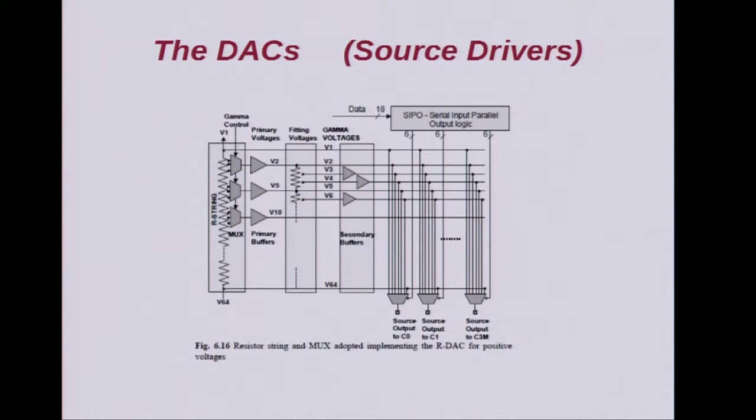The problem is that from month to month the mix of LCD material wasn't the same. It came out slightly different. Manufacturing tolerances of printing these LCD panels, all the wiring, overlaps, crosstalk on the capacitances, meant that from month to month the gamma kept changing. And that was okay in the first days of laptops and no pictures on them. But as they started using them more and more for television, they had to have a way of tweaking the gamma to get it a little bit closer to what they required.